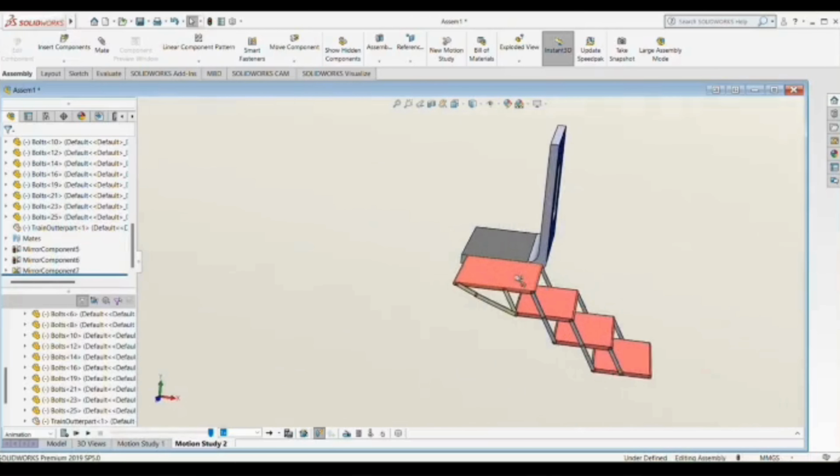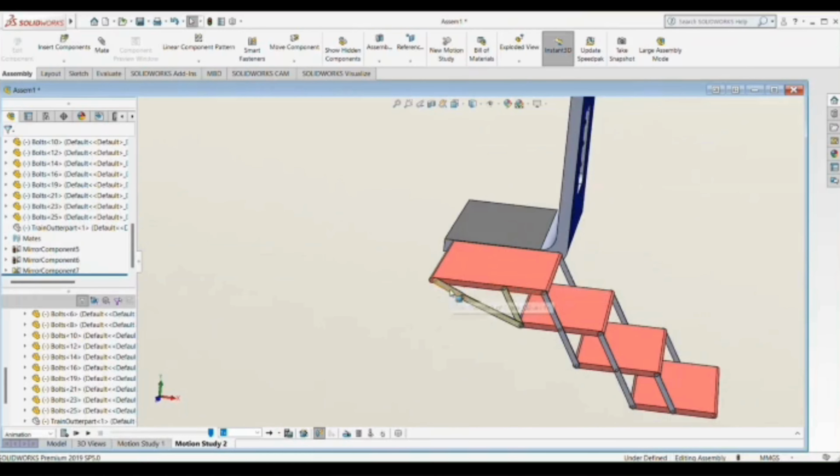Now, the 4R mechanism can be seen clearly and also the crank. Here, the red plate represents the ground link, which is fixed. This is a smaller link. This is the rocker. The remaining link is the coupler. We can label the mechanism as O2, A, B, O4.